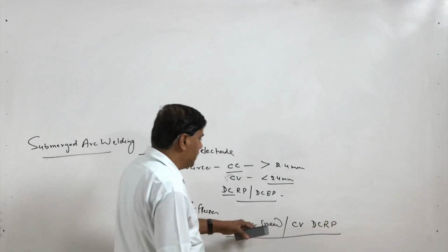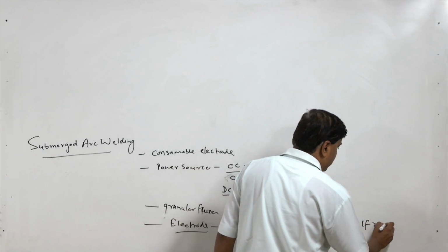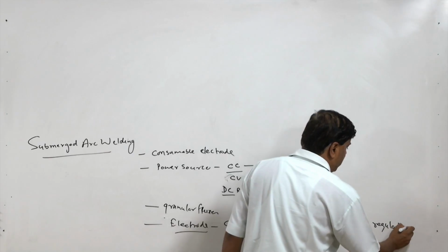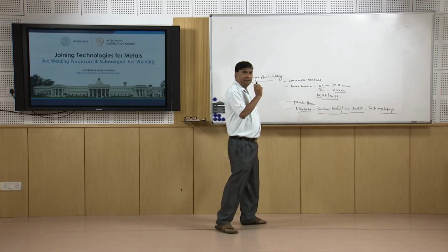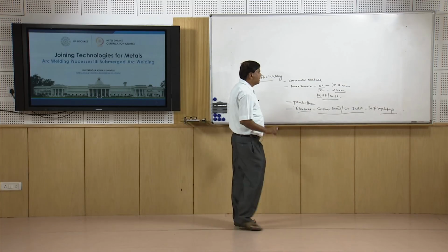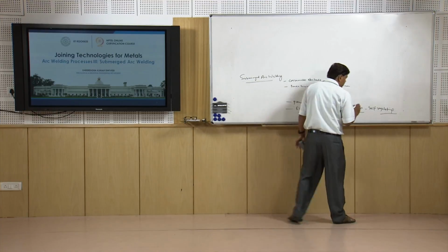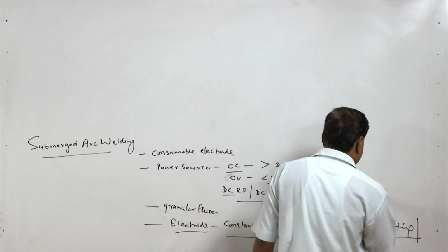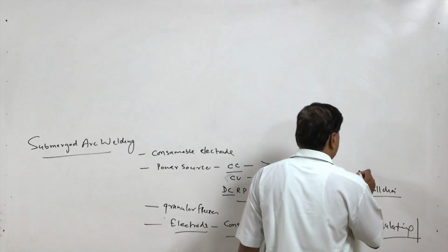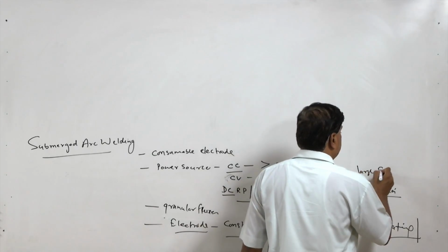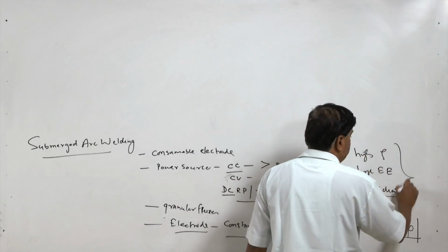This is the kind of combination which offers us the self regulating arc, which helps to maintain the arc length by adjusting the welding current, so that melting rate is adjusted under the conditions of the constant feeding of the electrode. And this is particularly suitable for the small dia electrodes, large electrode extension, and the high electrical resistivity materials.